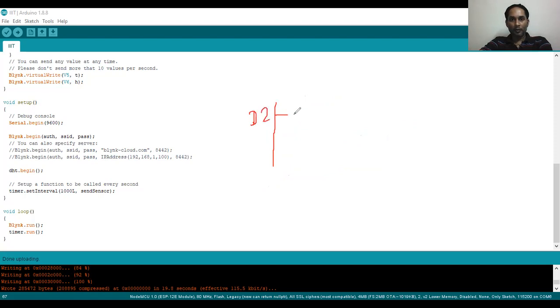Okay. So from D2 we have a relay here. The relay will have 1, 2, 3 and 1, 2, 3. One will go to source. It is written here as source, and then positive, negative. It needs 5-volt DC. I have used one Arduino.